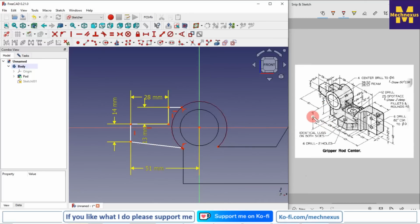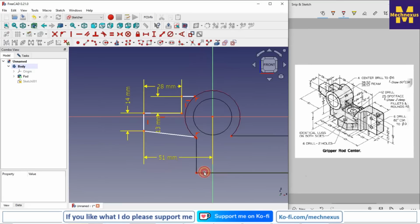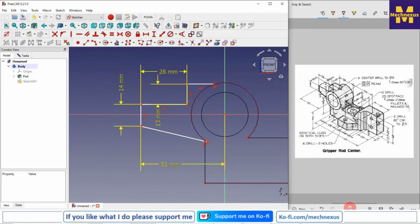And this angle is 14 degrees, which we can see here. So for this I will project this bottom edge. I will select this and give the angle of 14. Now if we see here, this line is in a vertical relation with the center. So I will select this point and add the vertical relation.